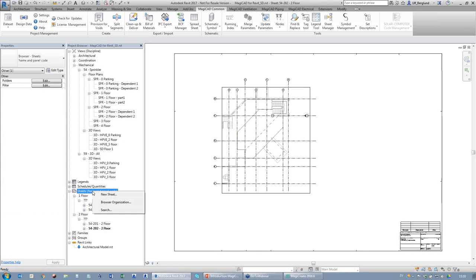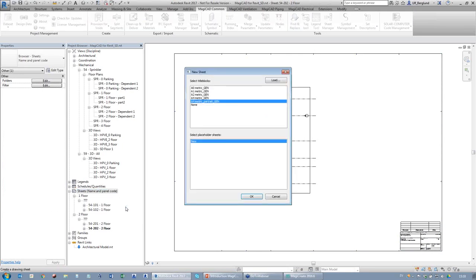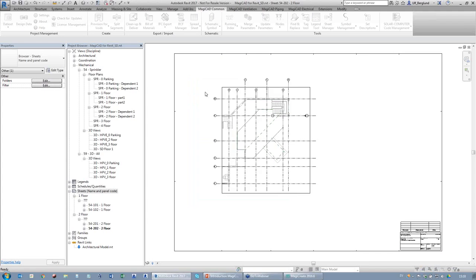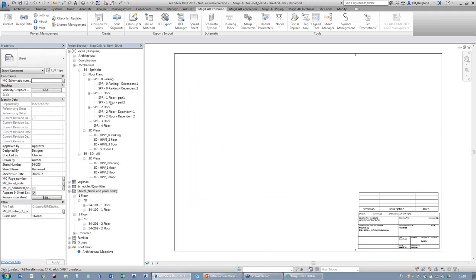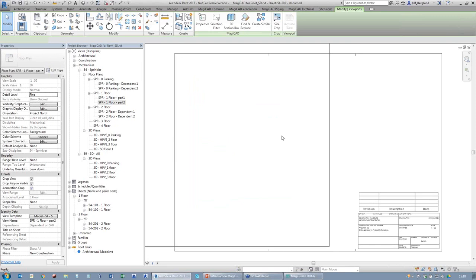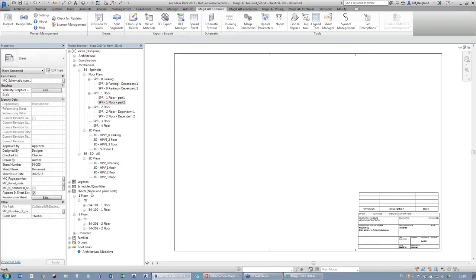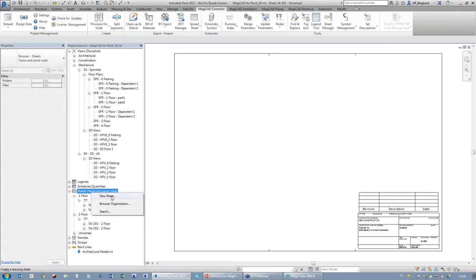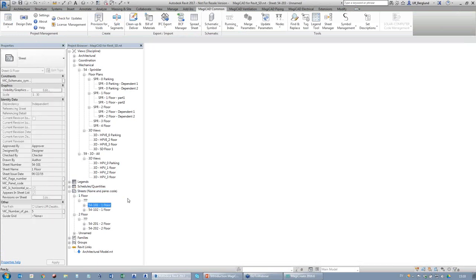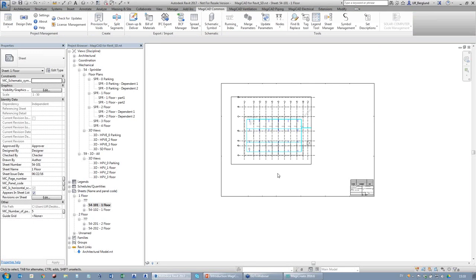If we don't have this sheet manager, we need to make these by ourselves. New sheet, select what kind of sheet we should have, drag a view into that, and then place it. And then when we're done, right click, select to choose the next one, and so on. And in this case, we had quite a few things in the drawing. Maybe you have some ruler, and maybe you have some explanation text, and maybe you have some detail view or something that's also placed in your drawing. When you use the sheet manager, it's quite fast to use it.